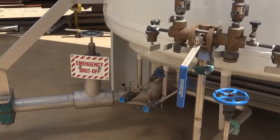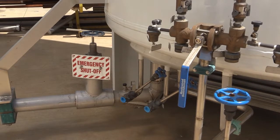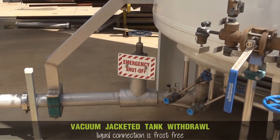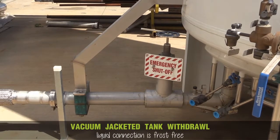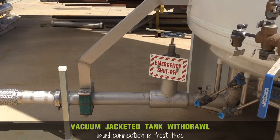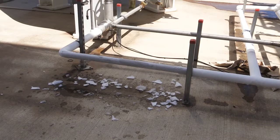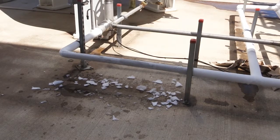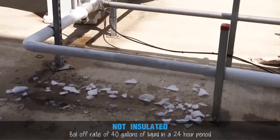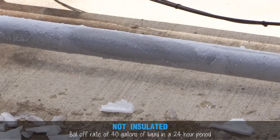The last detail of the supply tank is the connections required. The optimum choice for a liquid withdrawal is a vacuum jacketed tank withdrawal. This allows the liquid connection to be totally frost free and limits the amount of product loss and gas phased flow generation in the system. Some of our testing has indicated that in nitrogen service, 1 foot of pipe not insulated and kept frost-free in a 70-degree environment will boil off nearly 40 gallons of liquid per 24-hour period.